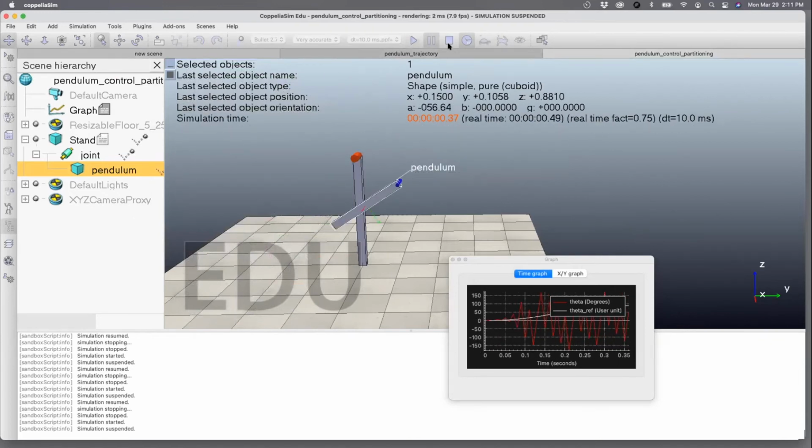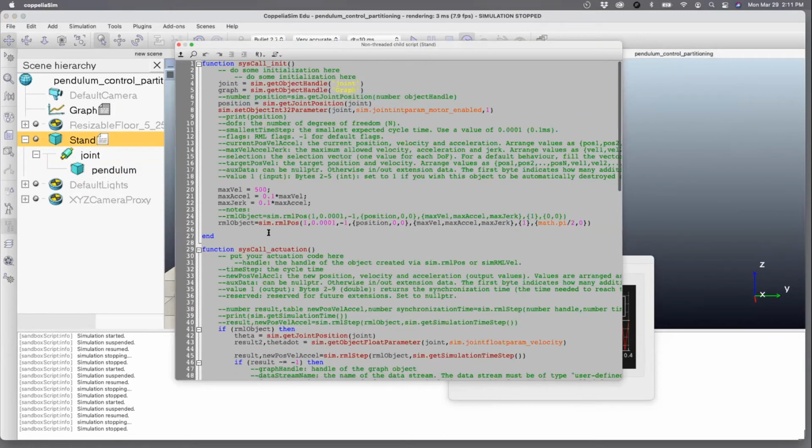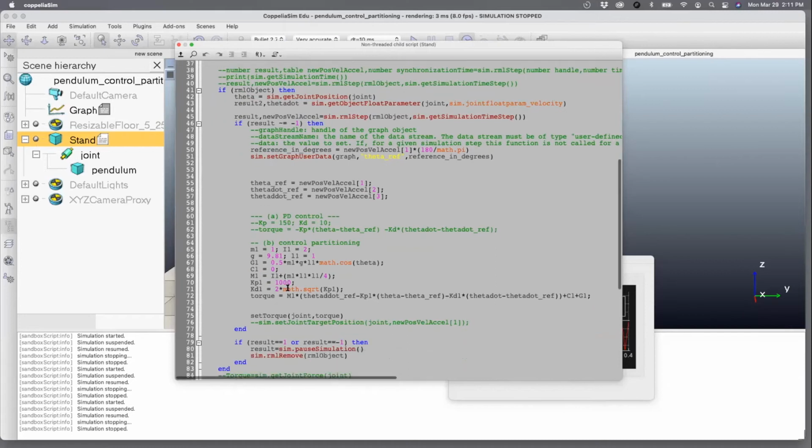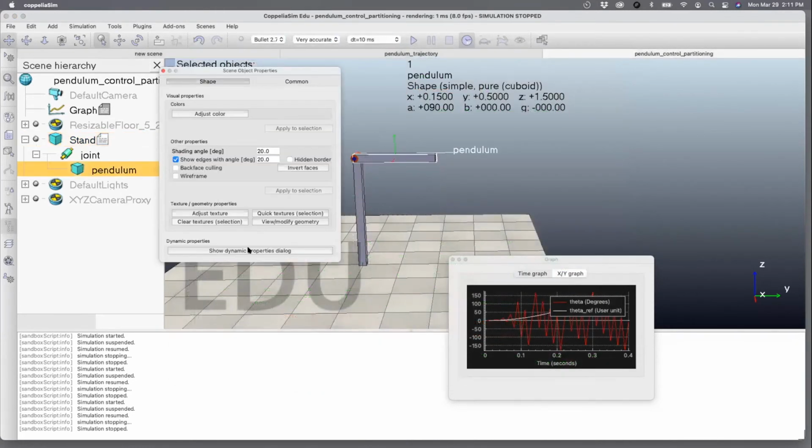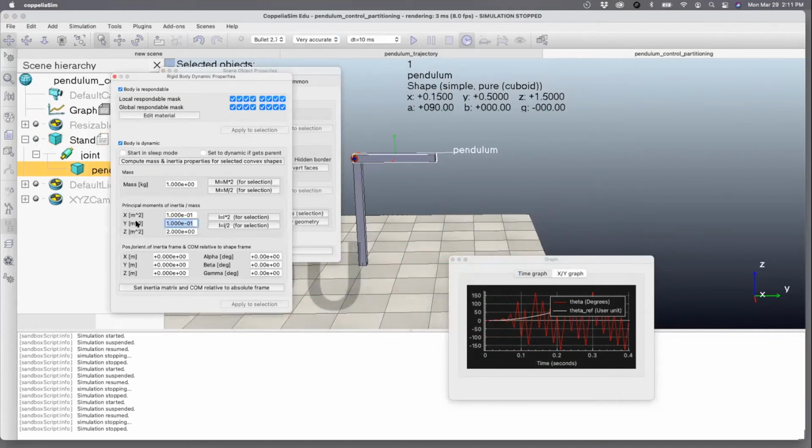Oh my god. So this happens when the inertias are badly scaled. One of them is too high and other is too low, and so it just moved off. You cannot have two small masses in this simulator because then it will fail. So I need to make it something reasonable, not close to 2 or of that order. Okay, so 4, 5, even 10 will be fine, I think, but you can't make it low.